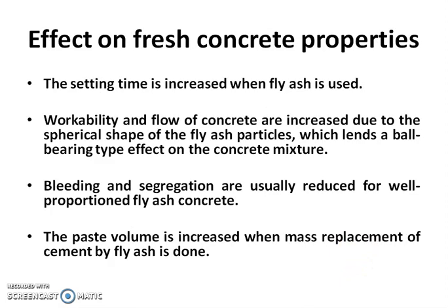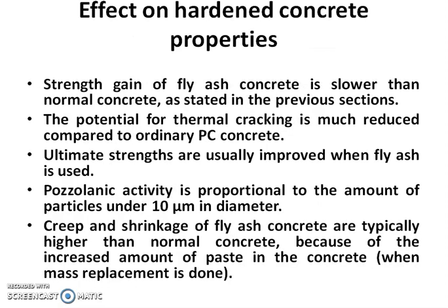What are the effects of this fly ash on fresh concrete properties? It increases the setting time, it increases the workability and the flow of concrete, and it reduces the segregation and bleeding. As the paste volume increases, it can be used as a replacement material for cement also.